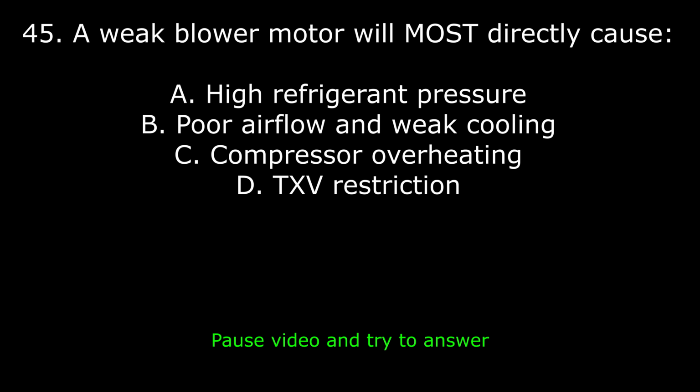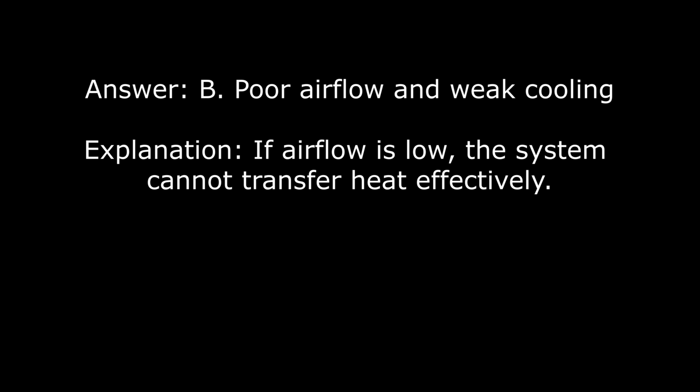45. A weak blower motor will most directly cause A. High refrigerant pressure. B. Poor airflow and weak cooling. C. Compressor overheating. D. TXV restriction. Answer. B. Poor airflow and weak cooling. Explanation. If airflow is low, the system cannot transfer heat effectively.